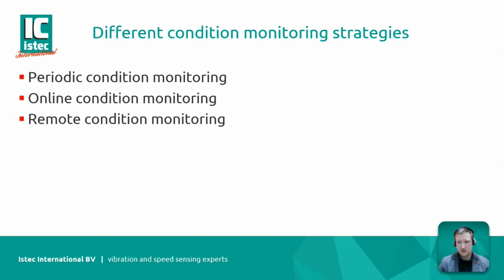It uses the same hardware, but it adds the possibility to do the analysis remotely. So a condition monitoring company like ESTEC can periodically check the vibrations, which are measured by the online condition monitoring system, and that can be used to determine trends like with the online condition monitoring, but it doesn't require any disturbance to the organization which is operating the turbine, because this all happens off site.